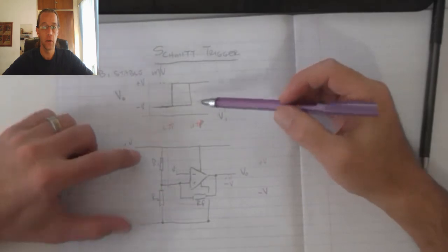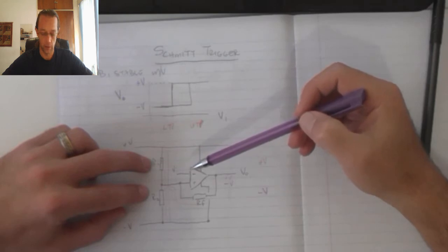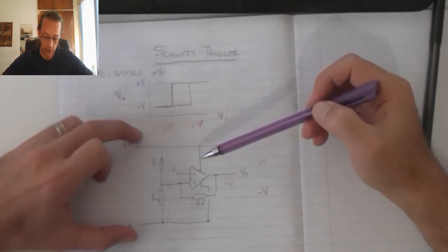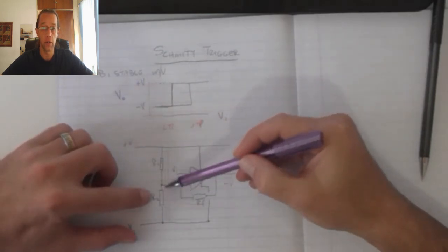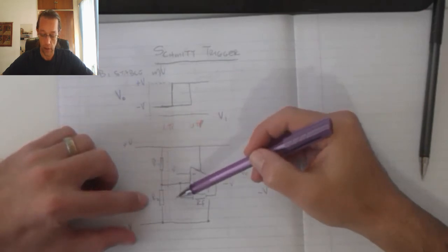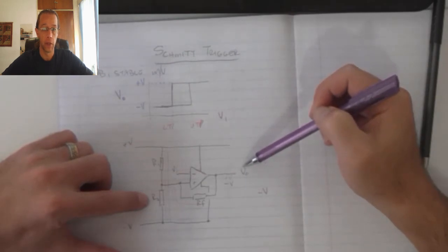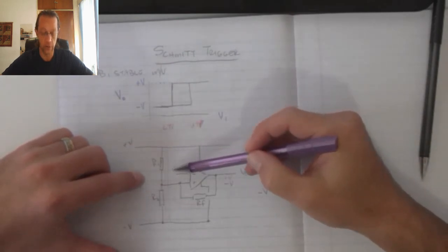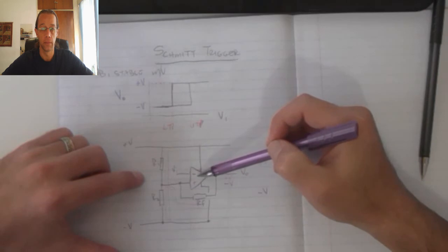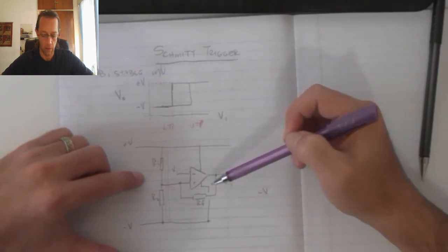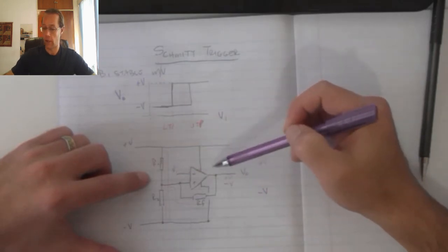Okay, now how these two work is the resistors R1 and R2 together serve as a voltage divider circuit between the supply, which is the positive and the negative, and the feedback resistor will develop a voltage in accordance with R2 and R1's voltages as well as the output. When the input moves below this voltage level that is generated by RF, then my output will switch on. When the input goes above that level, then my output will switch off.